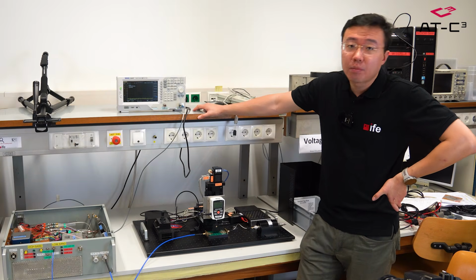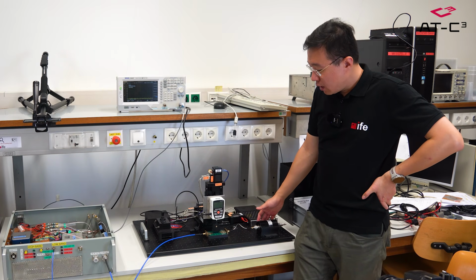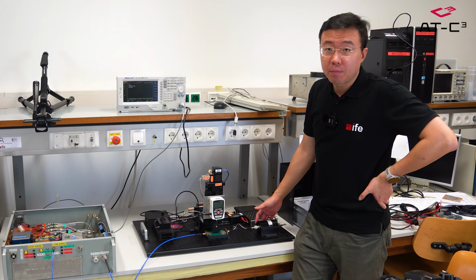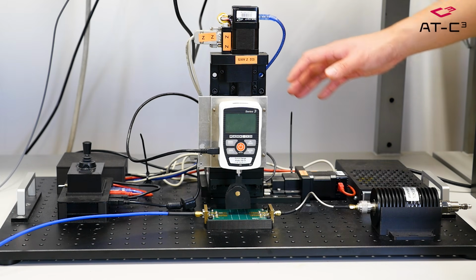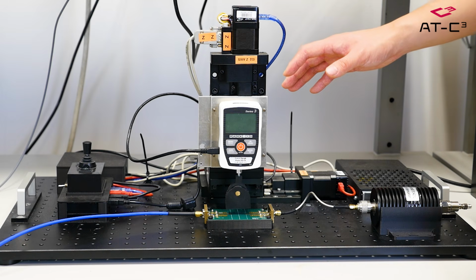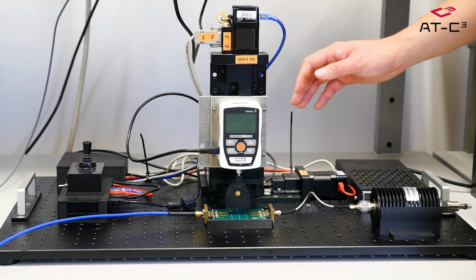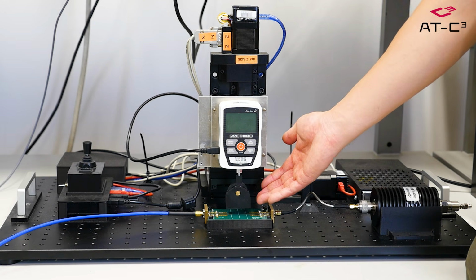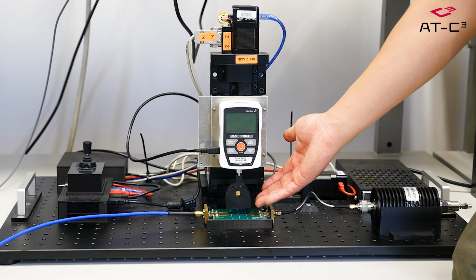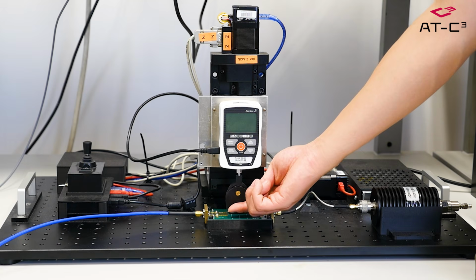So here, we come to our test fixture. Due to the contact harmonic having really low repeatability, the stability of the system is a critical part. In this case, we have this robot arm control system that helps us do the testing over and over again with a really consistent and stable press. We have the force gauge mounted on top, and then we have the adapter fixture for mounting the DUT. For example, when we want to test copper tape, we'll put a piece of copper tape over the top.